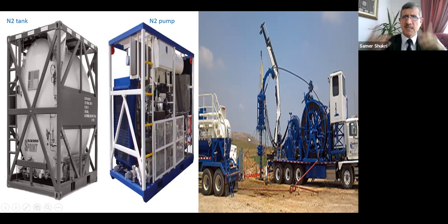In this case, we will offload the fluid in the well. If it is water, this water will be produced, will be offloaded from the well, and after that the reservoir fluid, oil, will be produced, and then we will get the well flowing. After that, we pull out of hole the coil tubing and divert the well to flow and rig down our equipment.